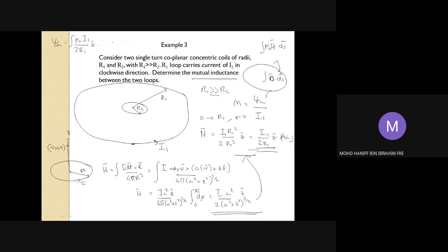and my ds. I'm using this equation, and my ds shall be equal to r dr d phi in the direction of Z, because we are using the cylindrical coordinate system. Based on this structure, your ds should be this ds on the top here, r dr d phi, and the direction should follow the direction of B, which is the Z direction. So the flux will be B dot ds, in which B will be mu naught H, and the ds based on this equation.